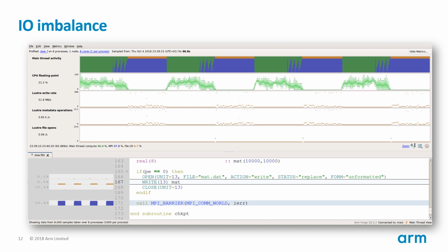If we increase the number of steps of our application, a new bottleneck appears. We can spot occurrences of a checkpointing function where data are dumped in a file in order to restart the simulation at the same point if the job stops. Often, when it comes to load balancing, the costliest function shown by the profiler is not the bottleneck, MPI barrier in this case. Instead, the bottleneck is the cheapest function, here the sequential I/O write. For I/O operations, prefer the use of an MPI I/O function, which will perform parallel I/O instead.